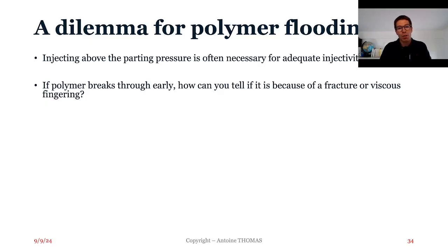And so the way to also understand is, if you decrease the rate and/or the viscosity, you should see a change of the Hall plot slope and the fracture closing. So monitoring is key, and of course the timing and concentration. If you observe polymer breakthrough, you inject 1000 ppm but you produce 75 ppm after 6 months, it's not a fracture.